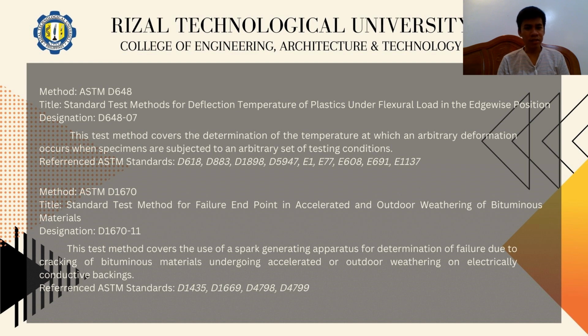Next is ASTM D1670, Standard Test Method for Failure Endpoint in Accelerated and Outdoor Weathering of Bituminous Materials. This test method covers the use of a spark generating apparatus for determination of failure due to cracking of bituminous materials undergoing accelerated or outdoor weathering on electrically conductive